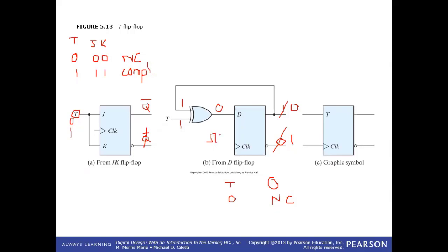Okay, that's a nice question. We are only assuming the outputs are changing because we are having a positive edge. The outputs would not change until and unless we have a positive edge over here or over here. Or if there was a not over here, the outputs would not have changed until and unless we have a negative edge over here and over here as well.